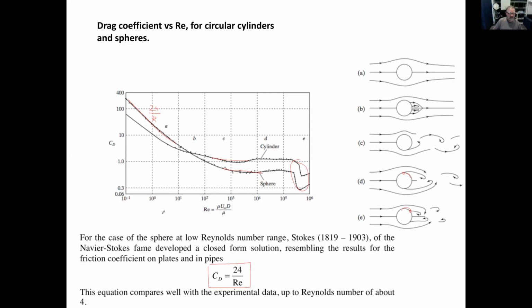There's an interesting example in airplane design. Let's say you have an airfoil and the flow goes around and then it would like to separate here. If it separates, that's not very good, because you get buffeting, or eventually the airplane will stall.